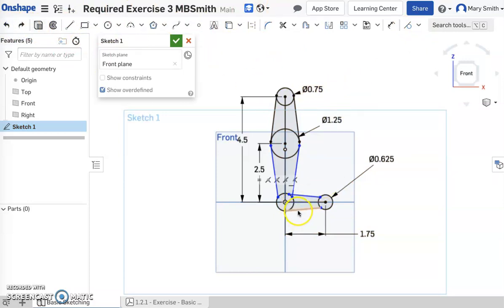And I know it's this line right here because when I made it, I wasn't paying attention. I'm just going to remake it, making sure that it is coincident only. Escape out of there. Now it's going to behave a little better when I tell it to be tangent, and I like it better like this. So select the tangent tool and then you can just make that tangent.